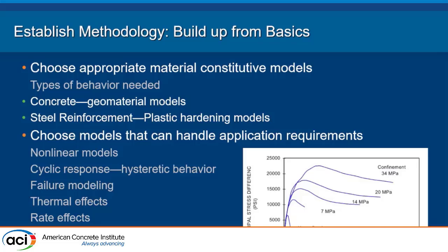Continuing on with establishing methodology, an important step is choosing appropriate constitutive models or material models. Not all are created equal. I don't know if there's any LS-DYNA users, but there's over 200 material models that are available. You have to go in and understand what they do, and maybe that goes back to the single element tests to really test them out.